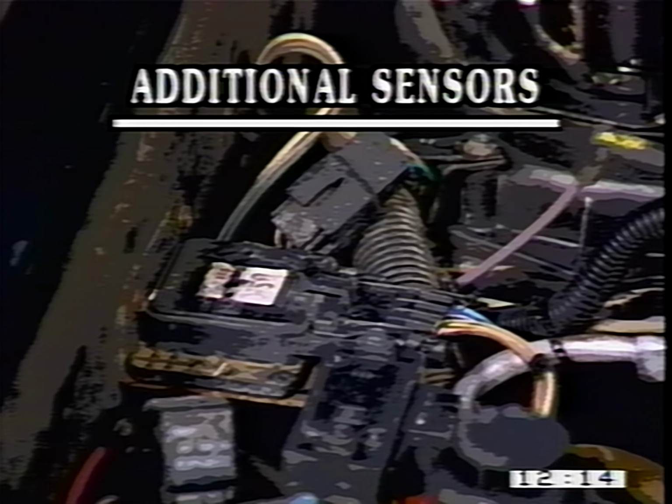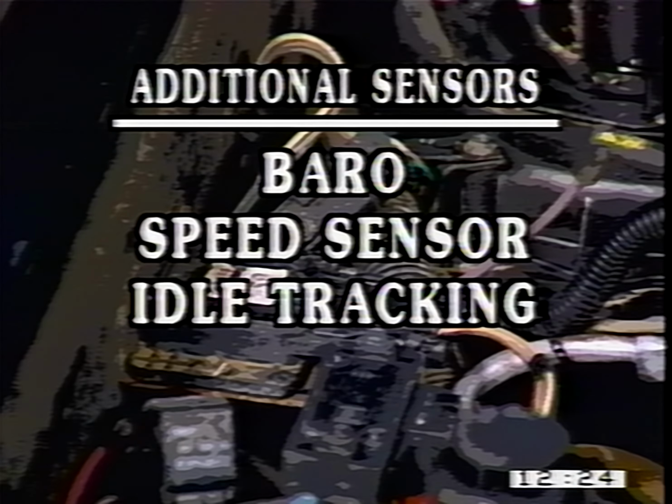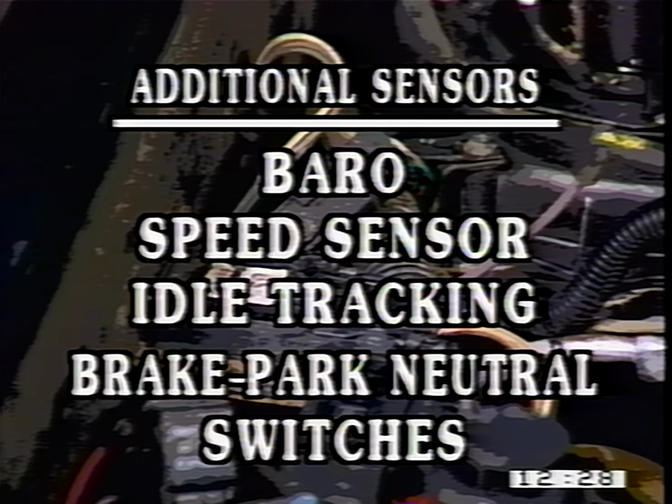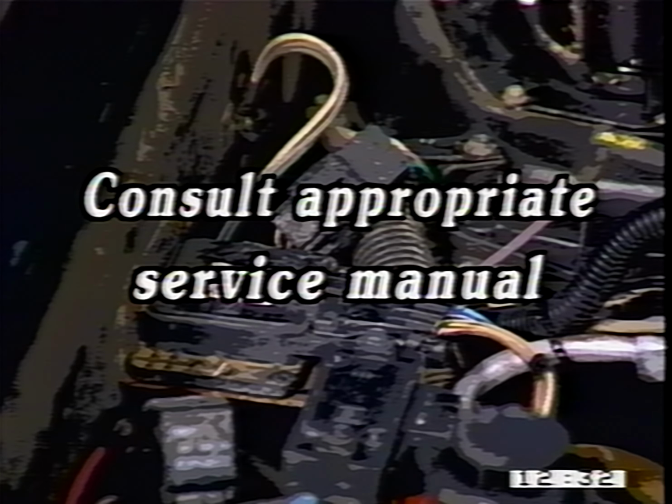The C3 system's ECM uses additional sensors depending on the application. Additional sensors include the baro sensor, the speed sensor, the idle tracking sensor, the brake sensor, and the park neutral switches. There are others. Be sure and consult the appropriate service manual for the complete list and locations of sensors, switches, and actuators.